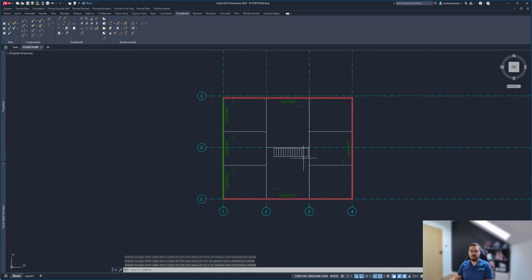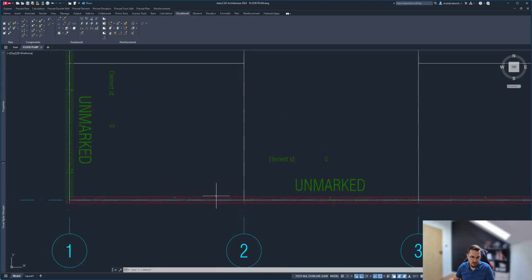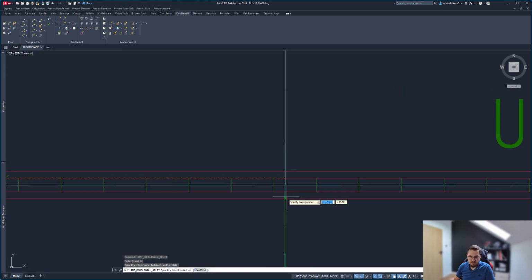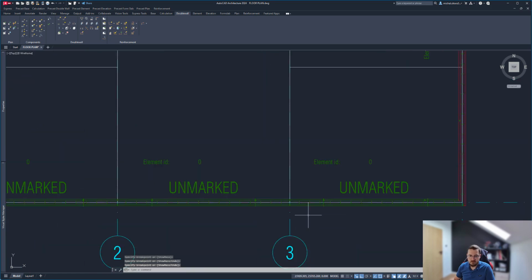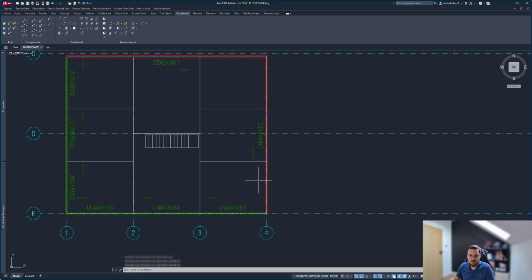And I immediately see that 3 walls, which are very long, gave out the warning that they're too big. Okay, and they're too big. If they are too big, then it's just a matter of actually splitting them. And to split them, we use this option. So let me select a wall, clearance between the walls, and click like that. And walls are now split and divided, lifts are added, all good.